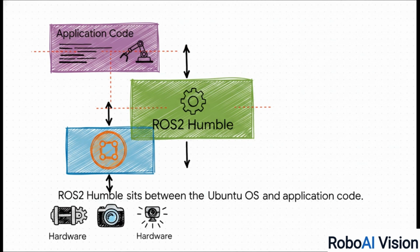On top of that, you usually have an operating system like Ubuntu. And right there in the middle sits ROS2 Humble. Above ROS2 is where your actual application code lives. Now, the huge takeaway here for you as a robotics developer is that you almost never write code that talks directly to the hardware. ROS2 handles all that messy hardware complexity for you.